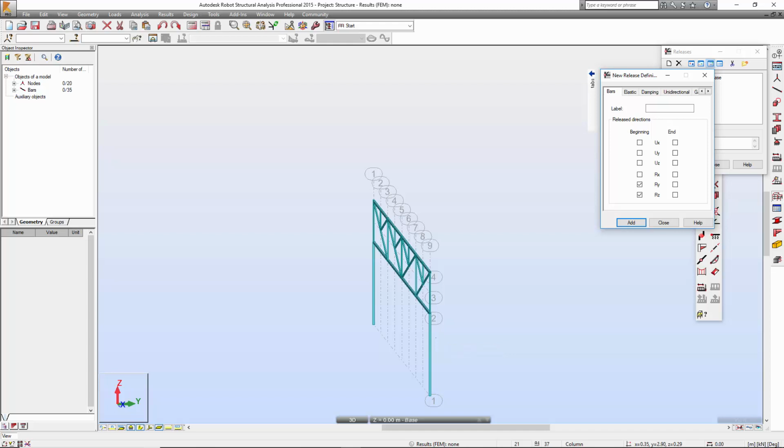So how about the rz direction? So rz means these structures about this axis, about this vertical, the column axis of this one. For this part, we do need to release, but sorry, about the Z direction is not going to be released, because otherwise this can spin along this direction, so we don't want to release. So this one should be connected to this one about the Z axis.